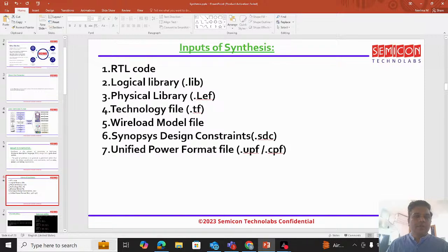Now, using this information and using the design specification and the design constraints, we try to come up with the clock uncertainty, the derates that need to be applied, the input delay and output delay that need to be applied at the interface, set driving cell, set drive at the inputs and set load at the outputs, right? Set max transition. So all the remaining constraints, including some of the generated clocks, right?